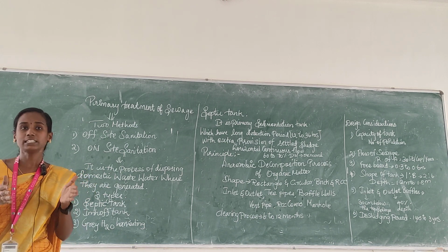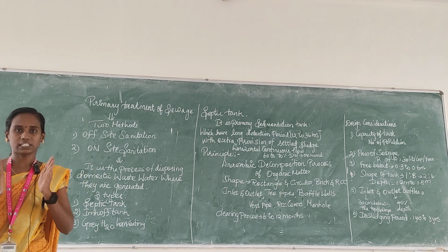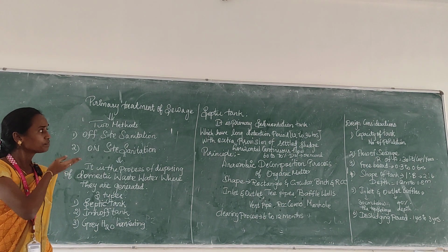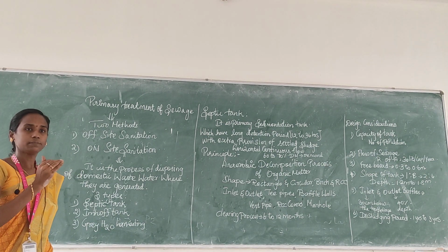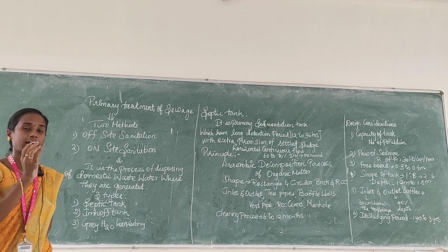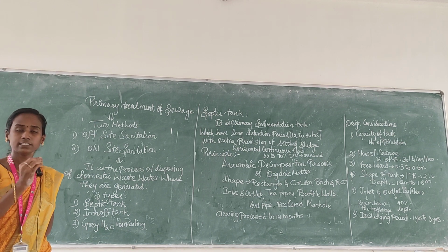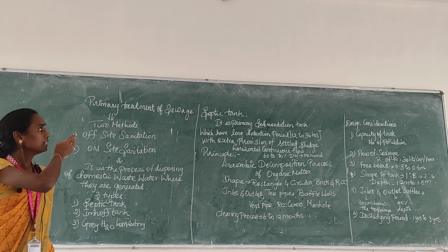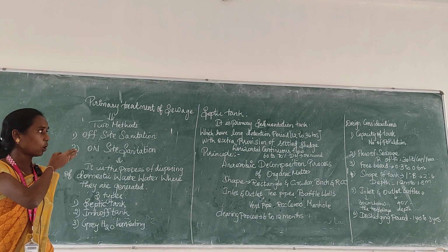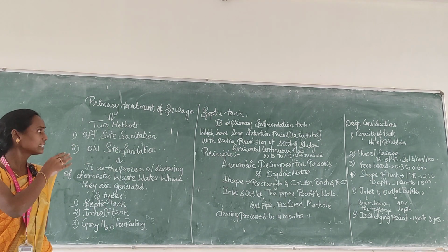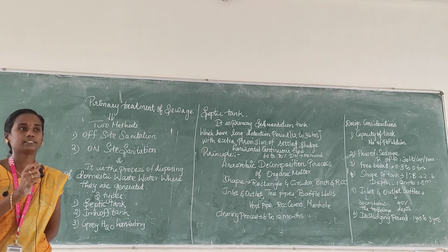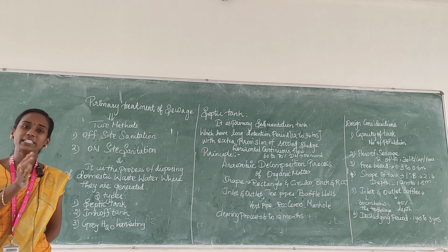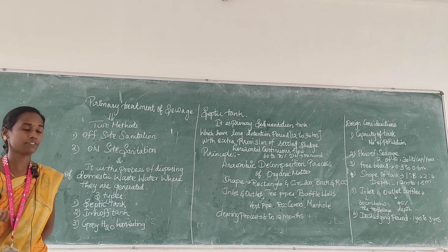A septic tank is the combination of a primary sedimentation tank with a long detention period. A sedimentation tank is nothing but a tank which settles the solid materials by using gravitational force, and which has a long detention period. A detention period is the time taken for settling the solid particles. So, it is the primary sedimentation tank which has a long detention period of 12 to 36 hours, with the extra provision of settled sludge. Sludge is nothing but the solid particles which are settled at the bottom of the tank. It may be in the form of a solid or it may be a semi-solid.